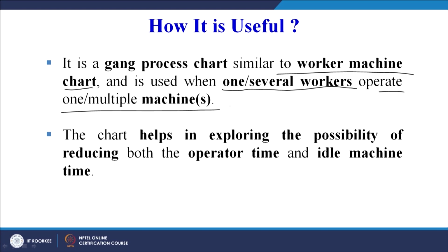What is the utility of the chart? The chart helps in exploring the possibility of reducing both the operator time and the idle machine time. So we want to optimize the time for which the operator is operating the machine, we want to reduce the idle time of the operator, and we want to reduce the idle time of the machine. That is our target when we draw the man machine chart. So we want to reduce both the operator time and the idle machine time.